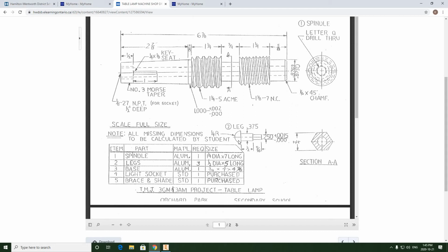So you're going to have to draw the largest diameter, where the fillet of 1/4 inch is, as 1/2 inch. And it's going to have to be extruded 1/4 inch. And then this extrusion, this 0.375 diameter, is extruded at a length of 1/2 inch. And then this smaller diameter, 0.250, is extruded to 5/16.